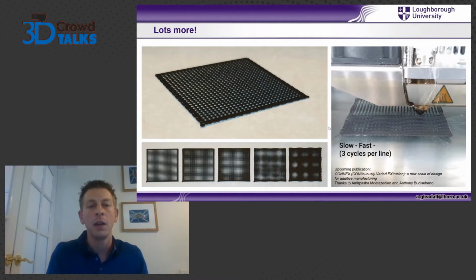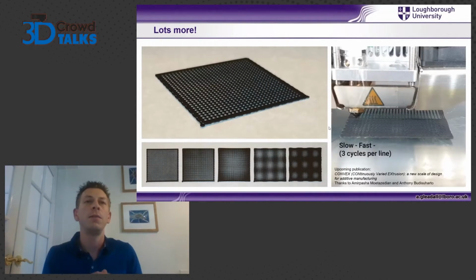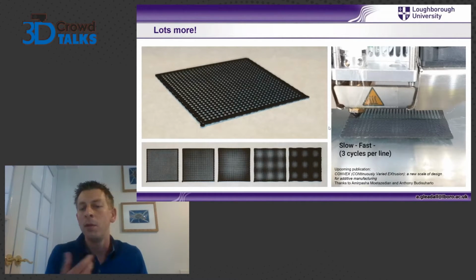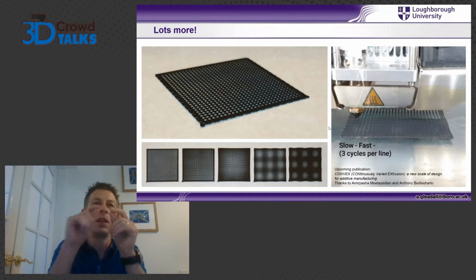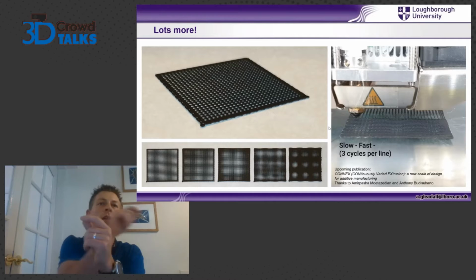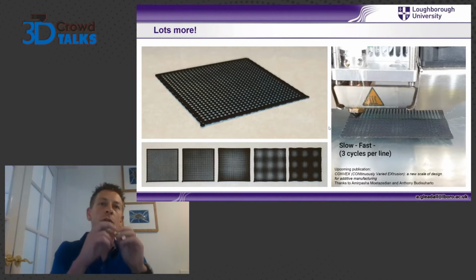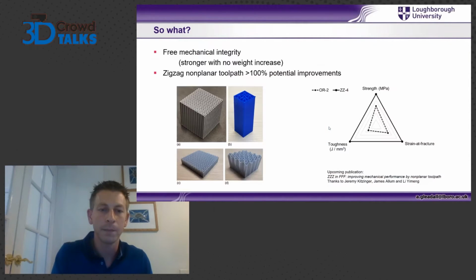And there is one thing: slicing software can vary the filament with variable infill for the final line, but it really doesn't do it well. And I've used that, and it's literally printed a little bit and then jumped back and printed another, and then back, and then it's just doing a really zigzaggy infill. And it is not the same as what we're doing here. It's more of just put the nozzle there and it kind of fills it. It's not a controlled gradient change of the filament width, from my experience anyway.